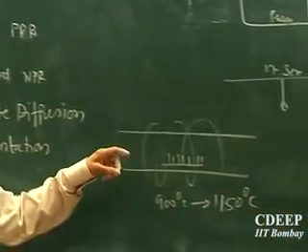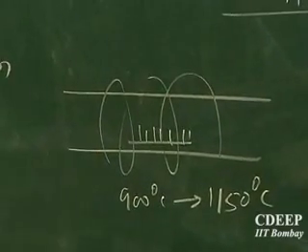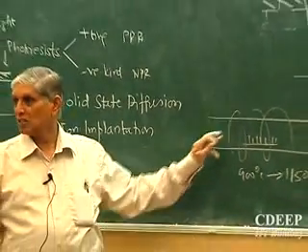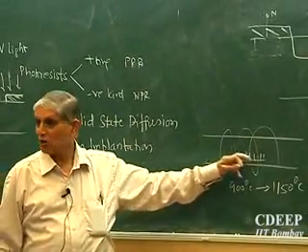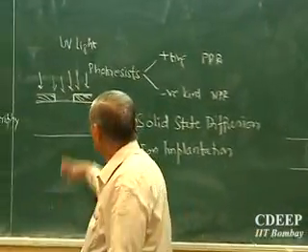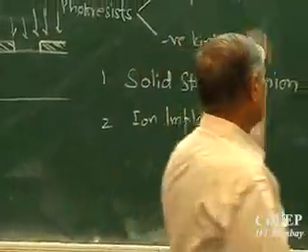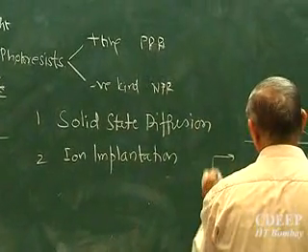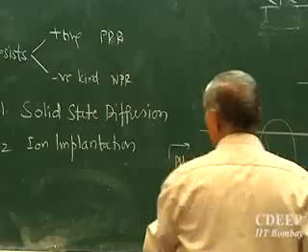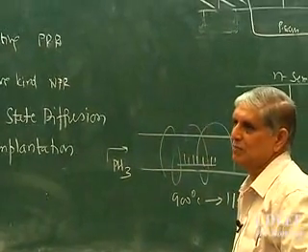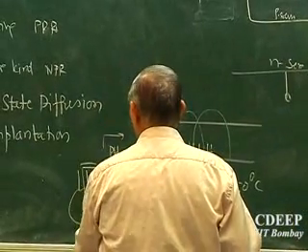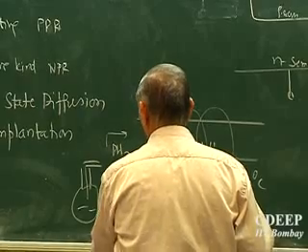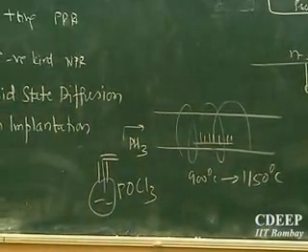Once you put these wafers in, they also get to this temperature. At that time we pass nitrogen, because even oxidation was done in the same way. We introduce oxygen or pure water steam, and then it oxidizes. Now for diffusion, I introduce impurities in a variety of ways. One way is a gas called phosphine, or a liquid in a bubbler, which is a solution called phosphorus oxychloride. This is for phosphorus too.